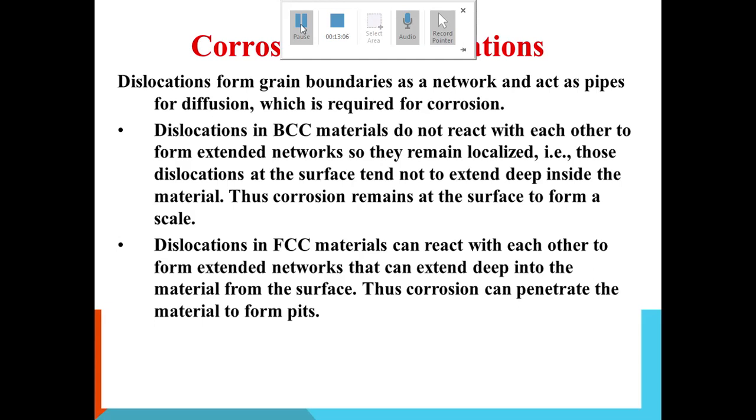Dislocations in face-centered cubic materials can react with each other to form extended networks that can extend deep into the material from the surface. Thus corrosion can penetrate the material to form pits. Which materials have face-centered cubic structure? Nickel, silver, copper, gold.